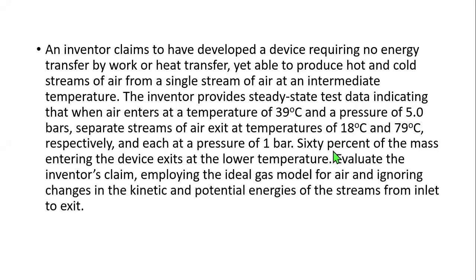Now, the rest of the question says that 60% of the mass entering the device exits at a lower temperature. So it means whatever is coming in, 60% of it would go out to the cold stream. It means 40% goes out to the hot stream. So we are going to evaluate the inventor's claim, employing the ideal gas model for air and ignoring changes in the kinetic and potential energies of the streams from inlet to exit.